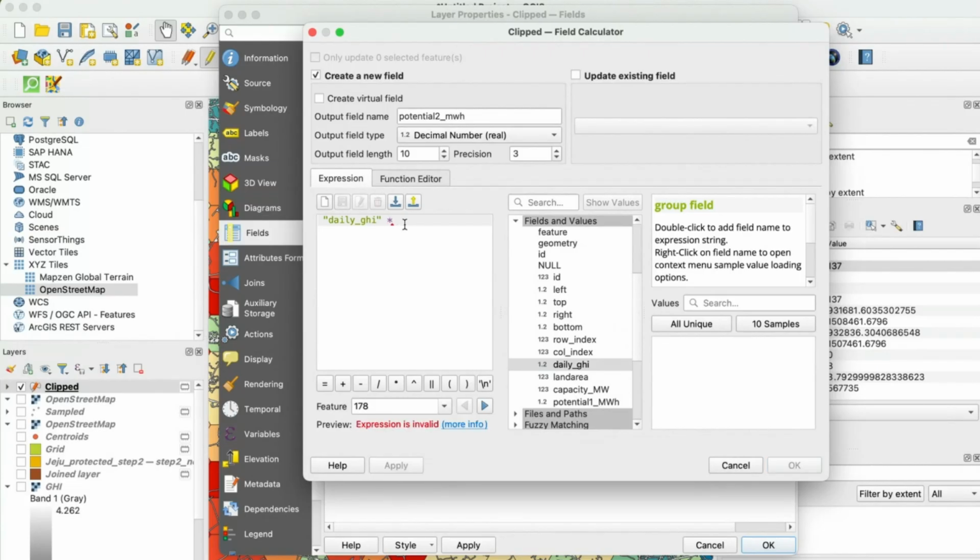So we need to multiply it with 365 to get a yearly output. And this output is in kilowatt hour, but we want to make it megawatt hour, right? So multiply it with 1,000. This already became a quite big number. But is this it? Is this all that we need? Actually, no. We need to add an efficiency because previously we used the capacity factor and the capacity of the system to calculate the output. So the capacity factor is fixed.